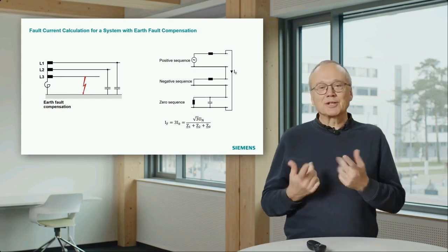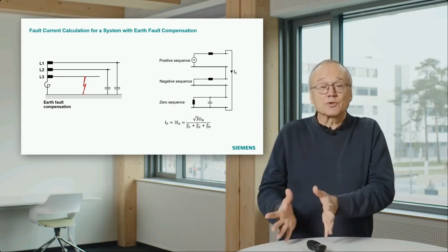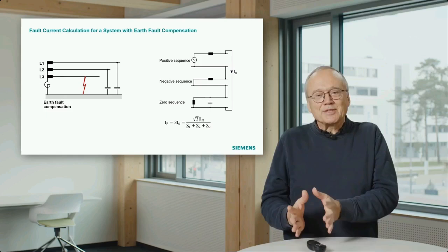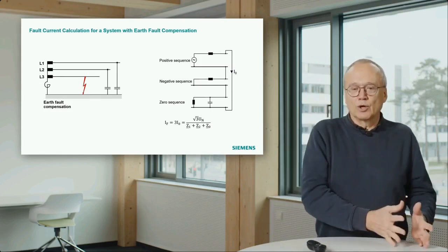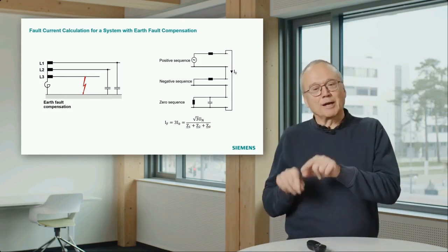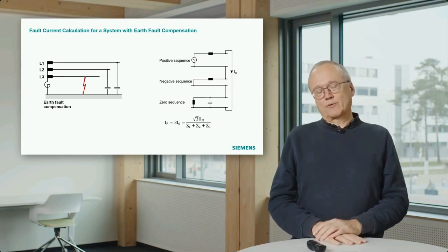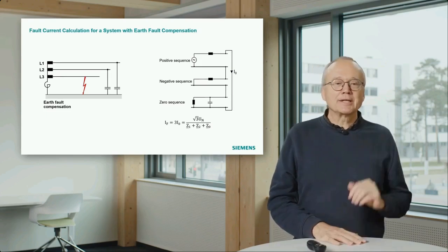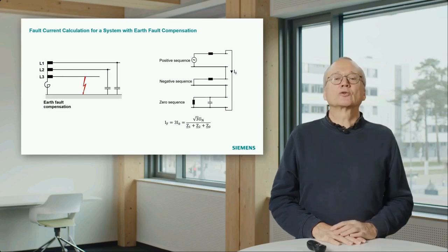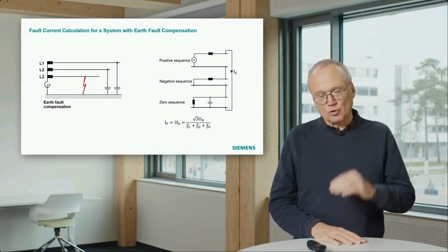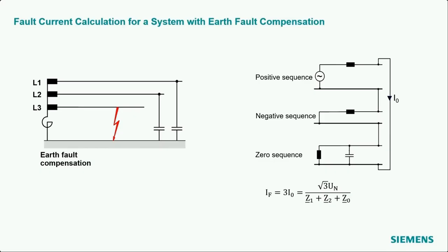Now the interesting question is, of course, that is the zero sequence world. Where can this inductance be in the real world so that it shows up at that point in the transformed world? And the result is we can put it into the Starpoint. That is shown in the real world diagram on the left side. There you see this coil, a big inductance, connecting the Starpoint to ground.